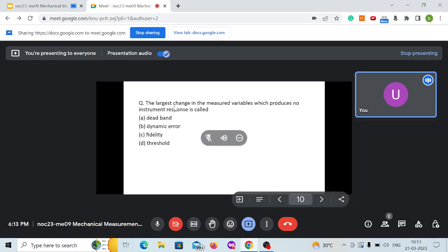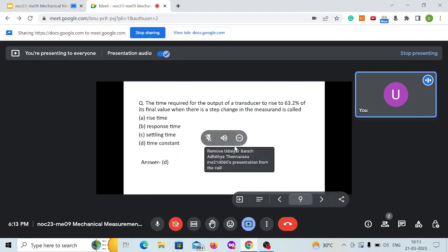If you see in this previous case, suppose you take the thermocouple example, you have a temperature bath at some temperature T, and the thermocouple is at room temperature. The maximum temperature it can reach is T, the fluid temperature, which has to be measured. So you write theta by theta naught, where theta is the temperature difference between the thermocouple and the fluid, which will be equal to e raised to power minus t by t star.